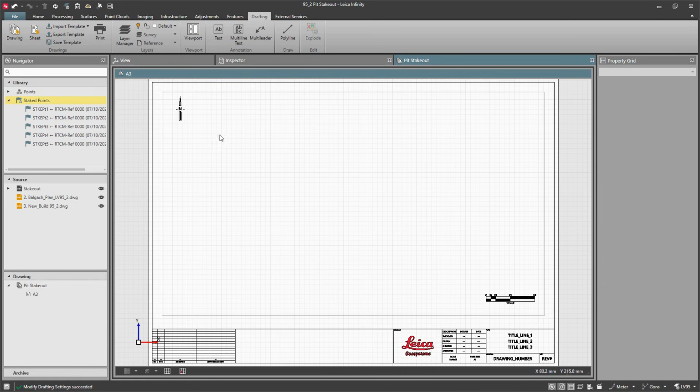The cursor is now shown as a cross. That means it is in drawing mode. The crosshair snaps to the grid node nearest to the cursor position. Draw the viewport in the sheet by selecting 2 points. A new viewport is created and shown in the sheet.